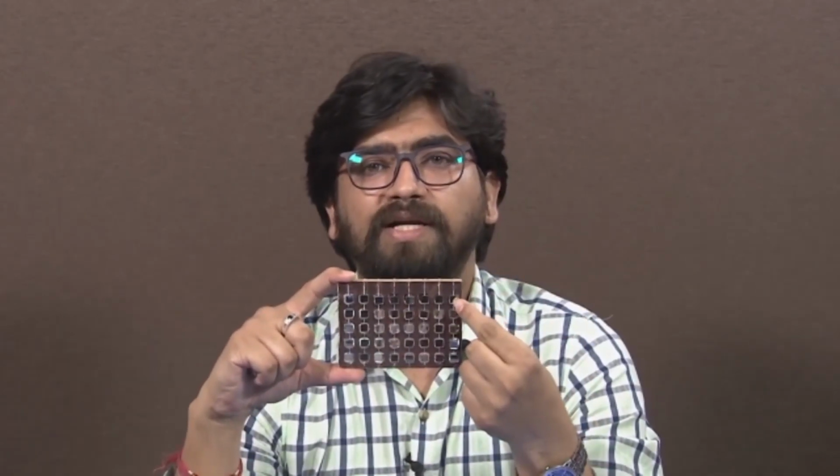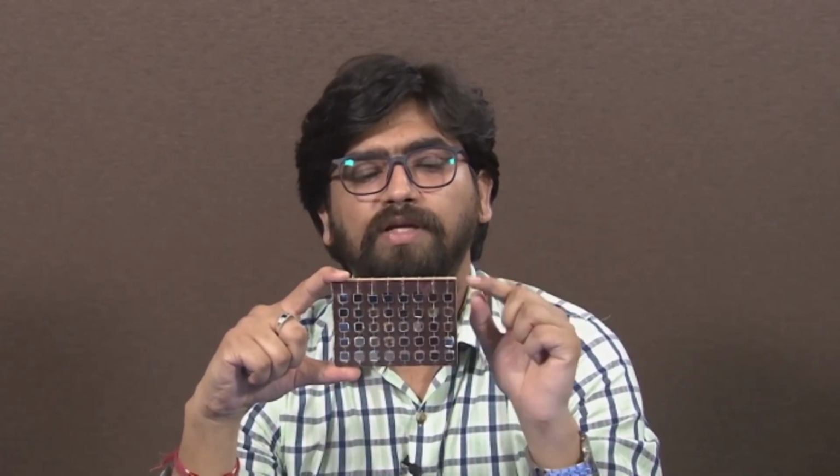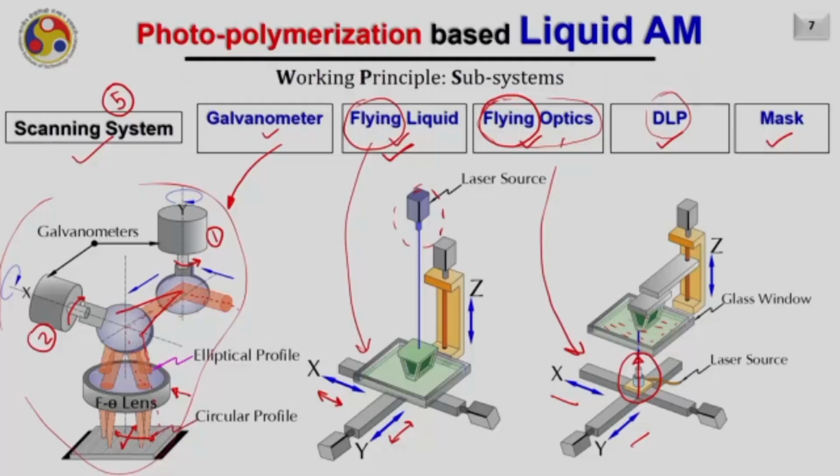The work I am doing here with the permanent magnet, in real life is done by the electromagnetic coils, and appropriately I just give the input. For example, I want to activate this mirror and deactivate this mirror, so I will give 1 0. Appropriately I can give 1 0 1 0 1 0 in an array, and hence the appropriate mirror will deflect the light at the particular location, and if the material is not there, it will deflect it somewhere else. So this is called DLP.